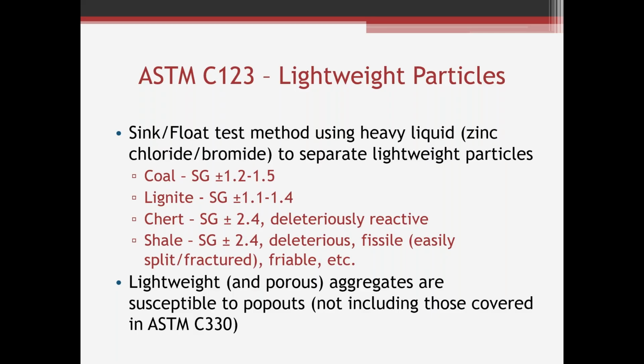This test is not done on aggregates that are covered by ASTM C330, which is the specification for lightweight aggregates for concrete. So, think of your Solite and all of those lightweight aggregates, the expanded shale aggregates; this test is not performed on those.